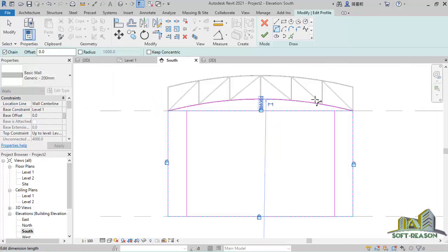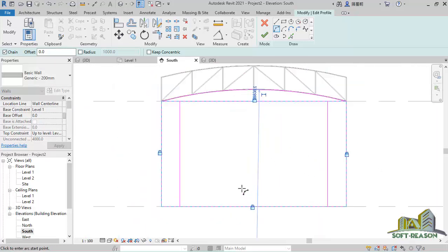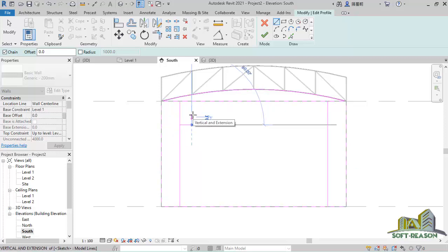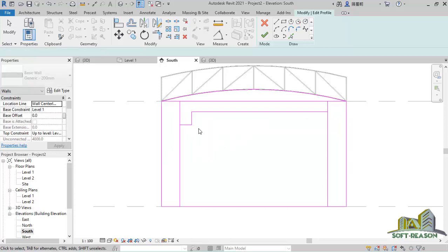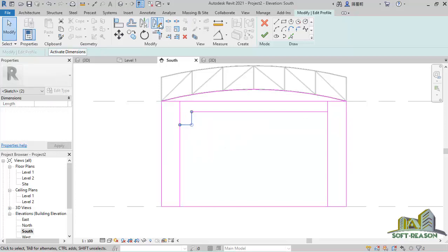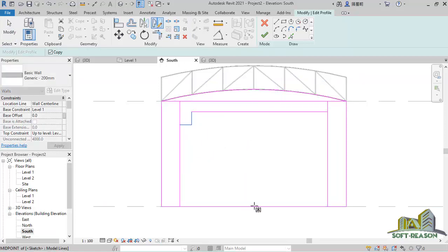After which I would like us to proceed in this wall editing. We will pick this wall at this point, let's say 900. From that point we move 450, enter, go up 500, and then you move to this point. Okay, deselect. I'd like us to use mirror, pick the center point, mirror it to that side, just like that.